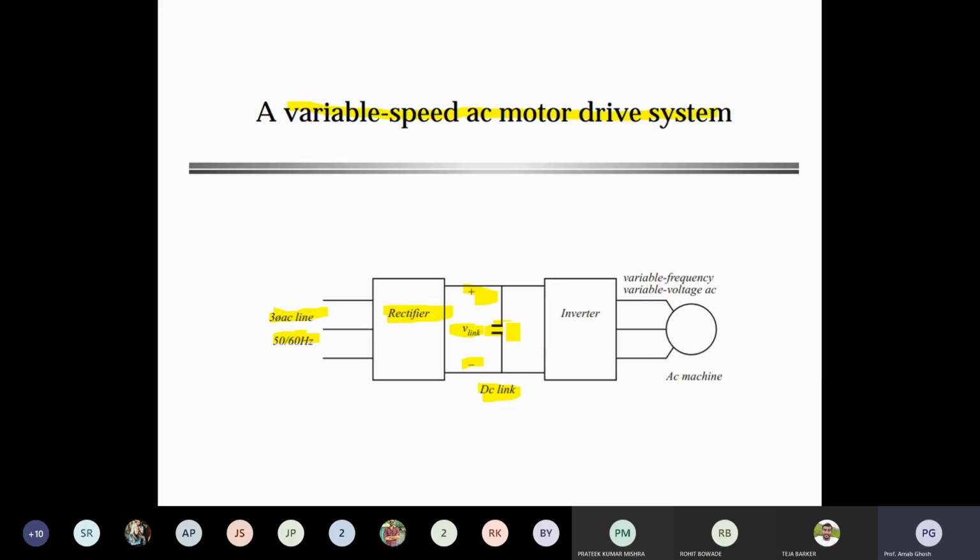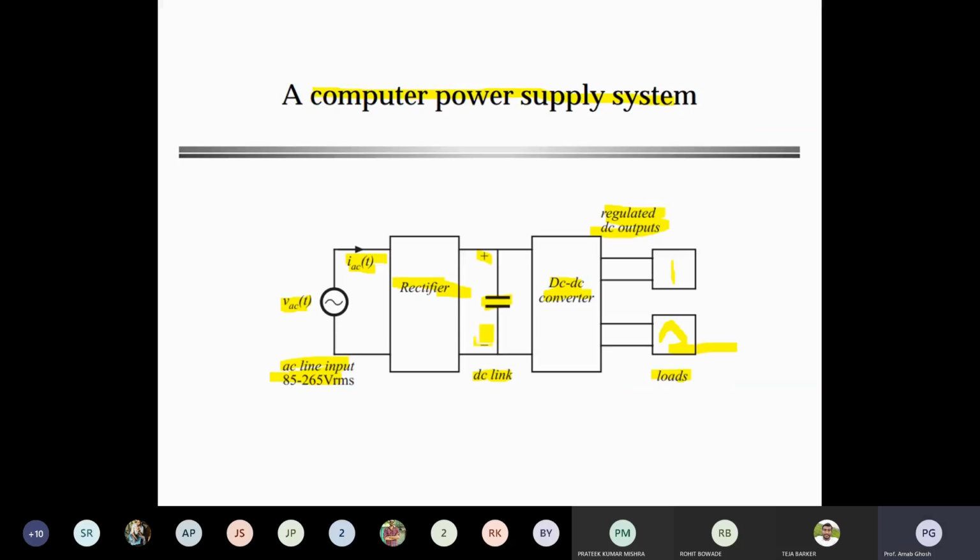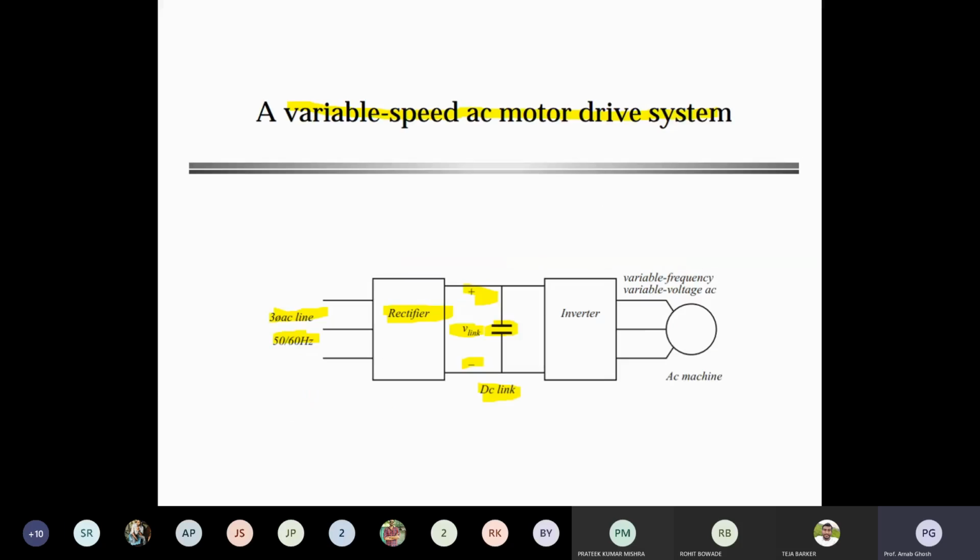But if you see how much voltage will be there, a three phase AC line means it will be nearer to 400 volt. So again you have to purchase a DC link capacitor. The range of the capacitor must be beyond 400 volt, otherwise it will burst, meaning it will be damaged. In the previous case, RMS is 265, so that capacitor will be up to 300 volt of DC. You can understand that as per the application, the parameter selection, that means the element selection, will be done by your side. Then you are using an inverter, because the inverter is the DC to AC conversion.